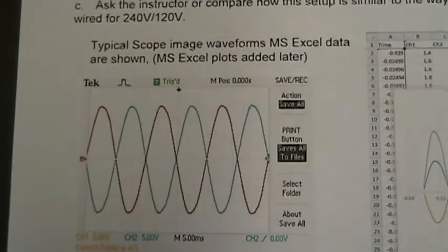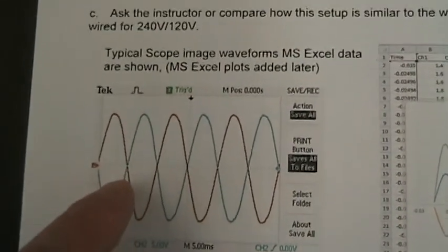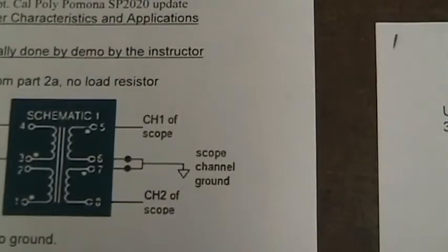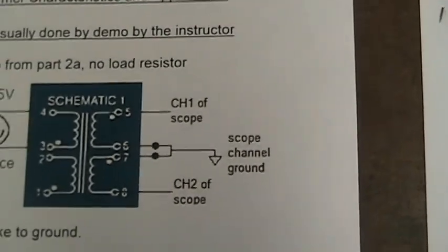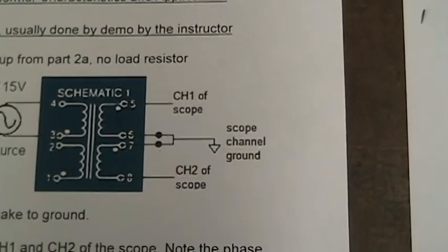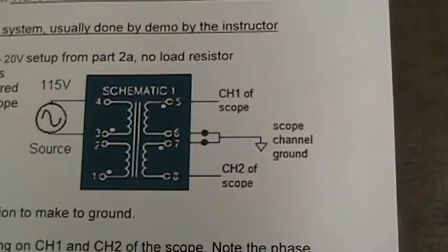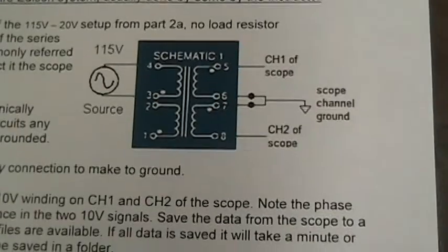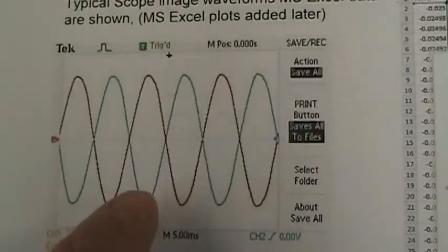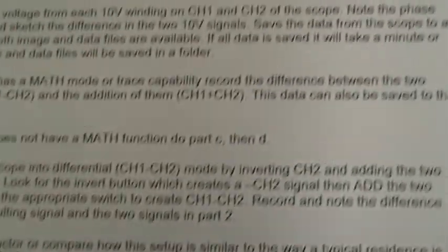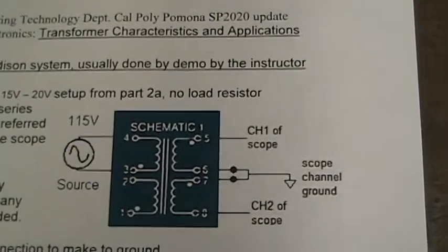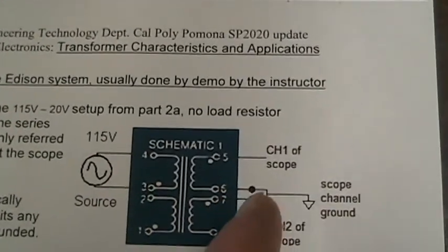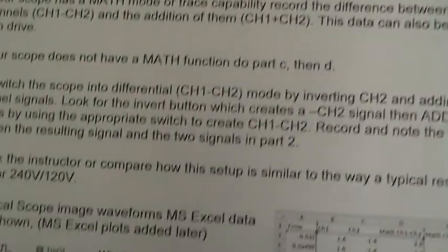Now when we interconnect this to the scope, you're going to see two different voltages. These two voltages come from the channel 1 and channel 2 off of the secondary. This middle winding, we would sometimes call the center tap, is going to be grounded with the scope, and because it's the output of a transformer, there's no galvanic connection between input and output, we can ground that one lead, right?